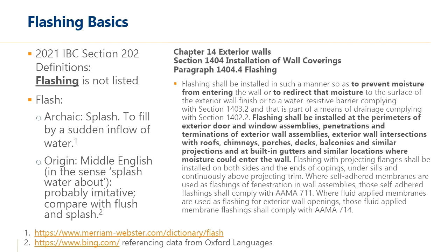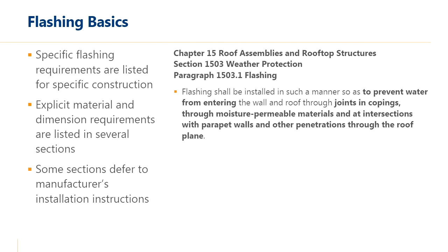It hasn't really told us what flashings are, but we understand it's to manage water and that we have to place them in many locations, particularly at intersections of systems or different changes in plane. If we look at the roof section, we have another paragraph that talks about flashing and similarly preventing water to enter and various locations that it's required.